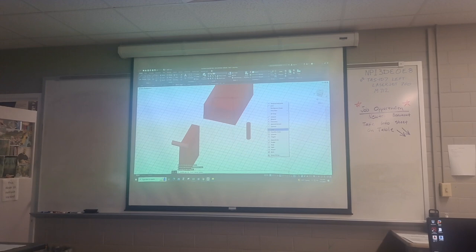So it kind of turns into a guessing game, but if you slowly just focus on what you're doing, try to spin your objects around where you can see it and isolate it. It'll make it a lot easier, and then also specify and force those object snap points on AutoCAD. So I'm gonna tell it the center of this end of that cylinder.